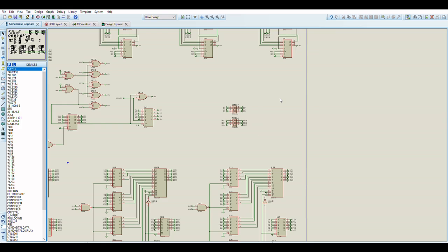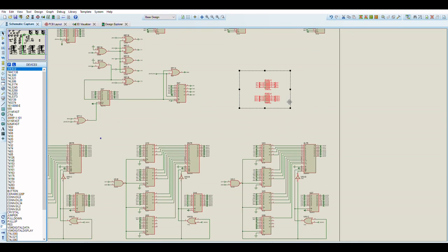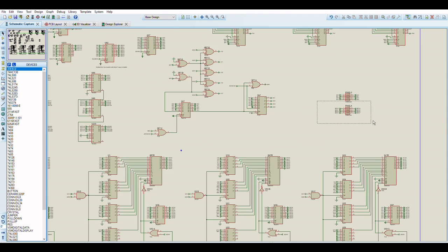The original BombJack hardware had character screen, sprites, and tile screen. The fourth plane was basically background color and ignored. So I added the notion of having the configurable output pixel plane here. So the tile board can output its pixels, and it has the option, but it's not mandatory, that the other pixel header will output the background color. It's not mandatory to connect this one up.